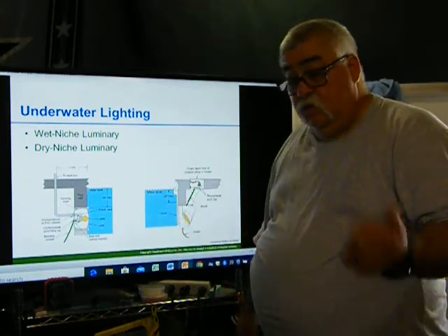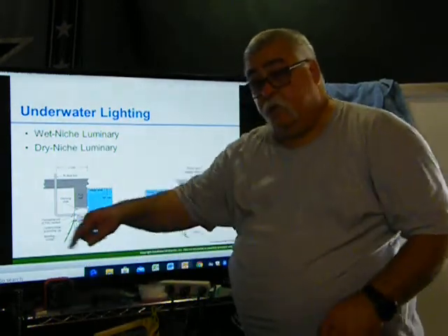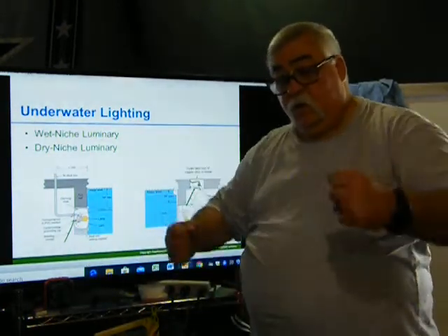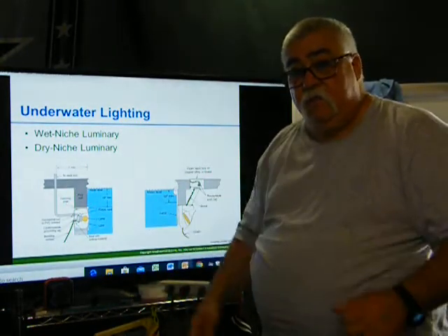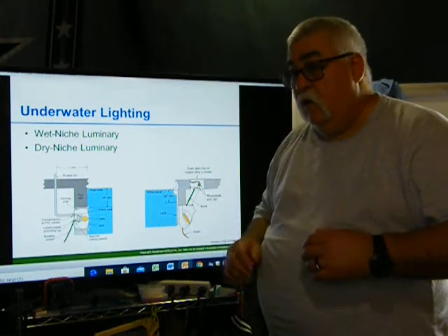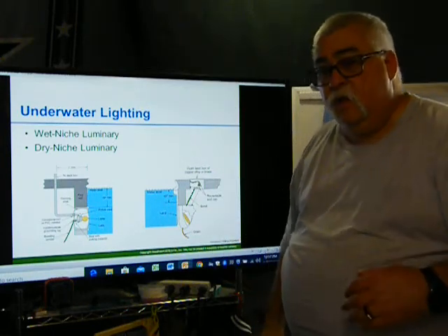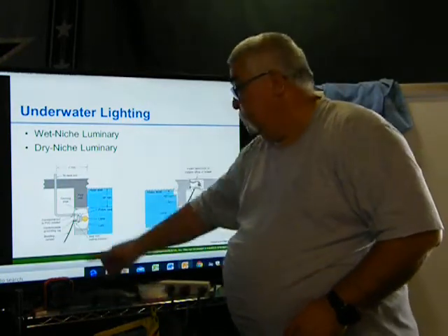Any rebar that was there was grounded off to this wire here. It's a bonding jumper. We had a bonding jumper going to all of it. We had a ladder, so the little mounts that went into the concrete, we had grounds on those. For the diving board, whatever, anything metal that was going into the concrete, we put a bonding jumper in. Okay.